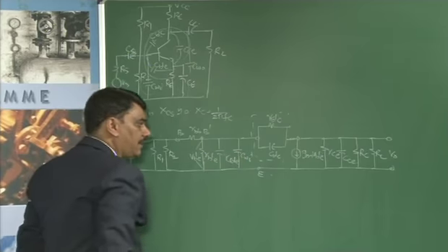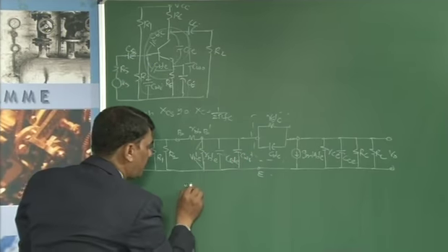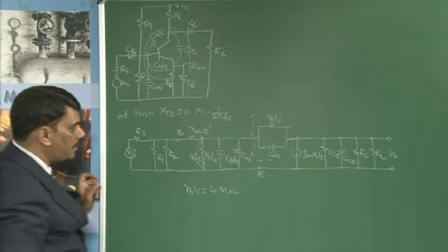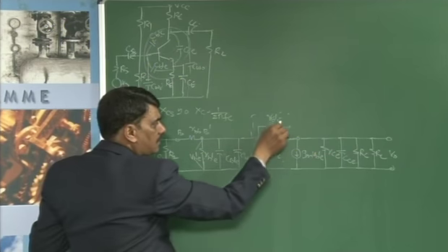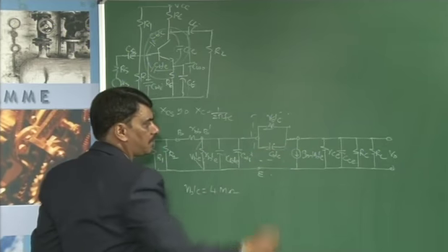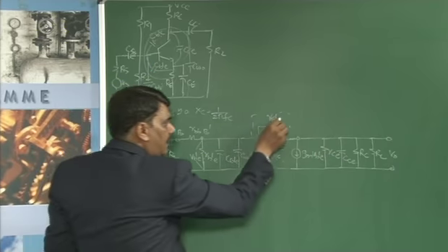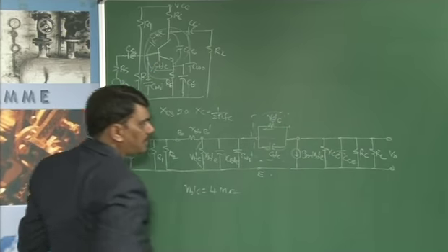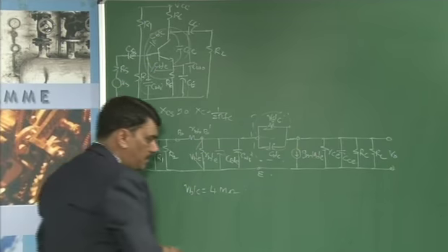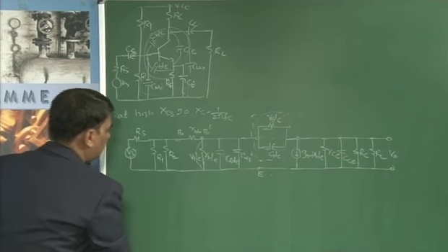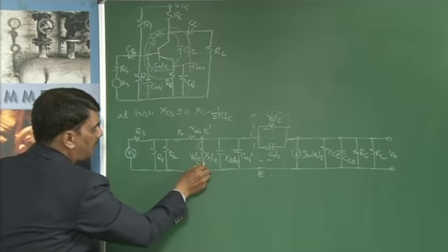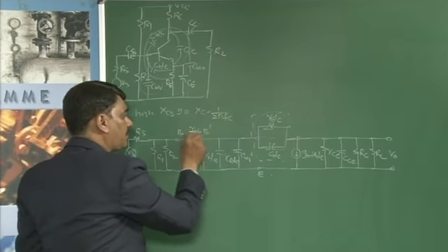Then the equivalent circuit is, we know already that RB'C is about 4 megaohms at 1.3 milliamperes. Because of this high input resistance, there is no current flowing in this branch. Instead, the current is always flowing through this path. Because of this reason, we neglect the open circuit resistance; we have neglected the effect of that resistance on the transistor at high frequency. Then this circuit is replaced with the equivalent circuit, we can redraw this. The resistance RBB' is negligibly small when compared to RB'E. Therefore, we can replace B with B'.